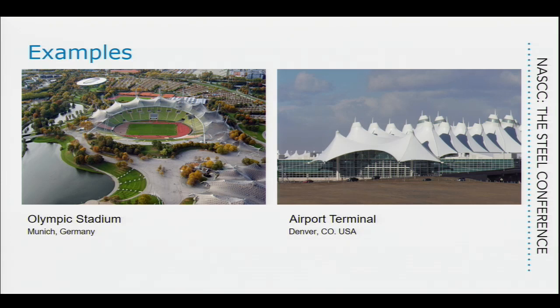And the way they did it is they actually created an 8-foot model of the structure. And this is not just an architectural aesthetics model. They actually created a structural model with actual steel mini members, mini cables, and everything. What he did is he would take a photo of the structure. He would hang weights all over the structure to simulate load, snow loads, wind loads. And then he would take another photo. He would overlap those photos, measure how much it would displace, and analyze how the structure behaved. So this was done in an era of very, very smart people that kind of started this whole process along.